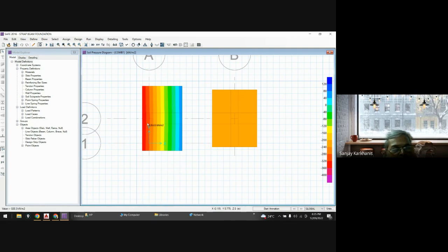Now you cannot increase the footing on this side and this side with a large area, because in that case the bending moment under the footing will be excessive, and you will have to provide more and more reinforcement at the bottom, and even then it may not be suitable.